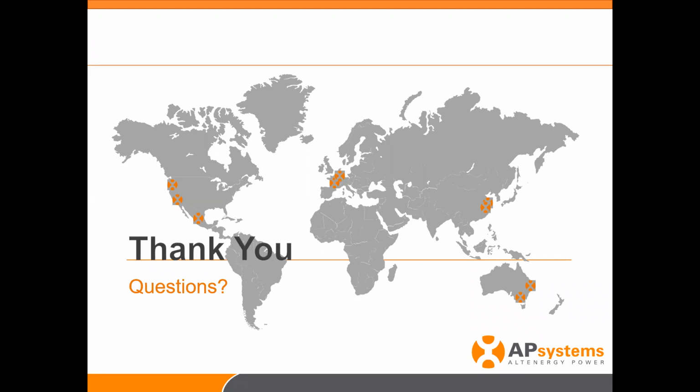The PTC, or in some countries the NOCT, is more the practical output they expect you to get out of that module. That will only degrade over time, and most module manufacturers will print that on their spec sheets. Over a 10-year period, they guarantee 80% of the value. So we know that the modules are going to degrade over time. So right sizing the modules from the start, pushing that inverter as hard as you can for its lifetime, is really the key component here.